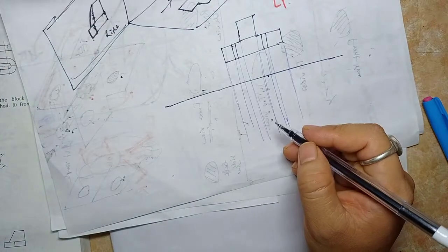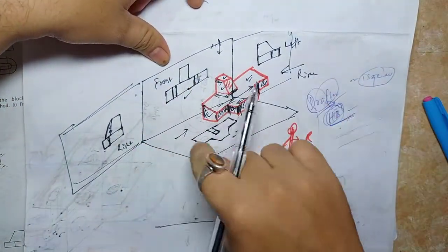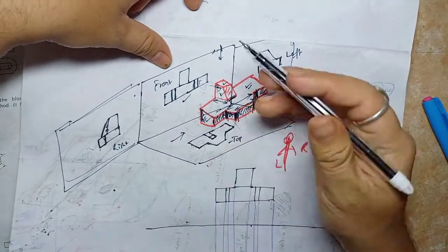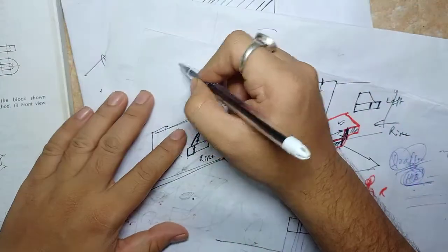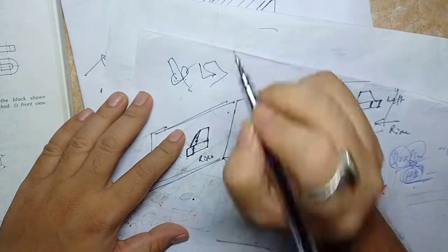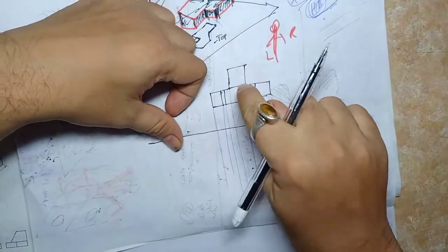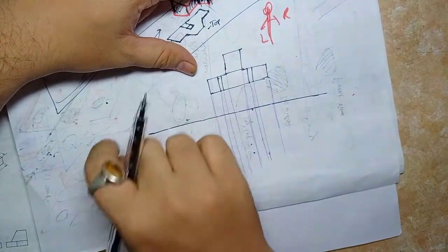Now, you always draw roughly first. That will always help you. For the views, there is no need to draw exactly by making a plane or everything. You can draw anywhere. This is my front view, and it will look like this. The top view will look like this, anywhere. But that will help you at the beginning. A rough diagram will help you. Once you draw your front view, you can obtain your top view and side views with the help of it.